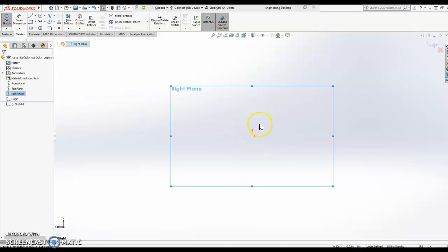I can see my centerline axes here. Now the one thing that's a little bit different with this, because we are going to be doing revolved parts, is I want to exploit that entire idea of revolving. So I want to be able to use lines of symmetry. To do that, we're going to put in a special kind of line. We're not just going to use a regular line. We are going to use a center line.